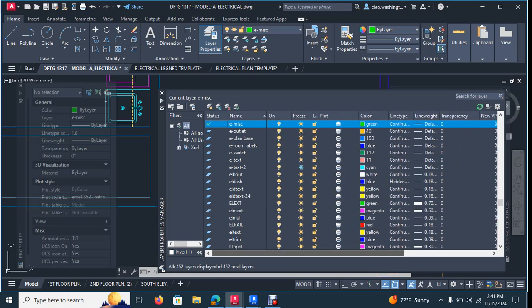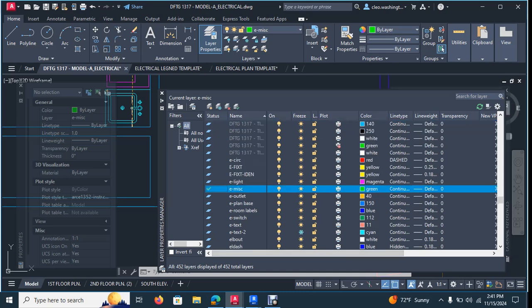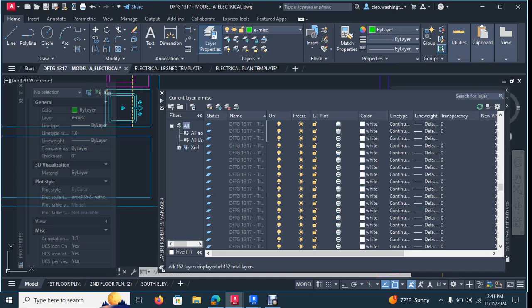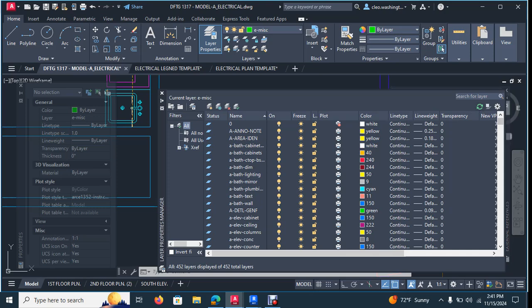Okay. Oh yeah. So you see this little printer right here? Okay. And we'll stay here. We'll come back down to that. I just want to show you something. You can tell it what layers you want to print and what layers you don't want to print. If you remember when we were setting up the viewports, we had that set on layer 0 because we don't want that viewport to show. You see how the printer here, now it's set to print, but typically when you have that red minus, that means when you actually print, that line work is not going to show up. So I don't think I covered this with you guys. Each layer you can tell it whether you want it to print or not.